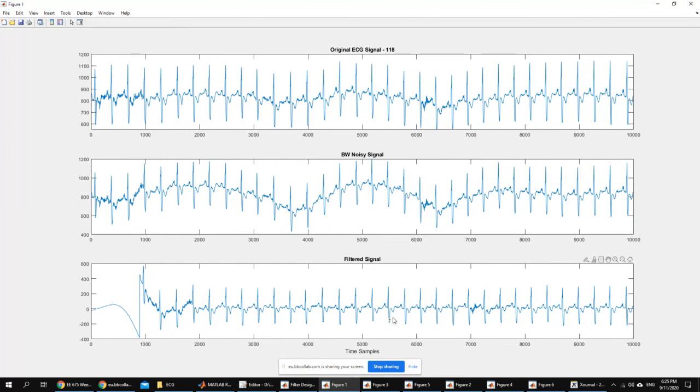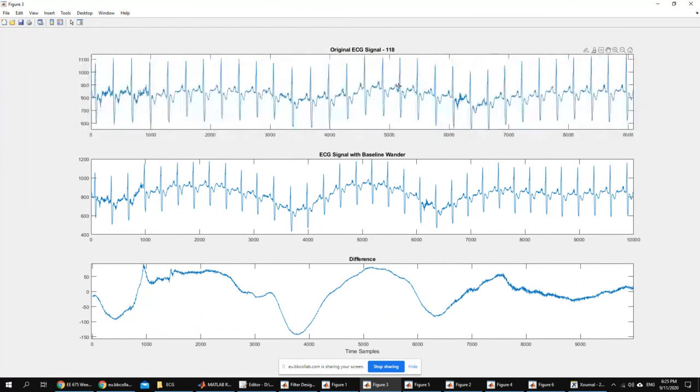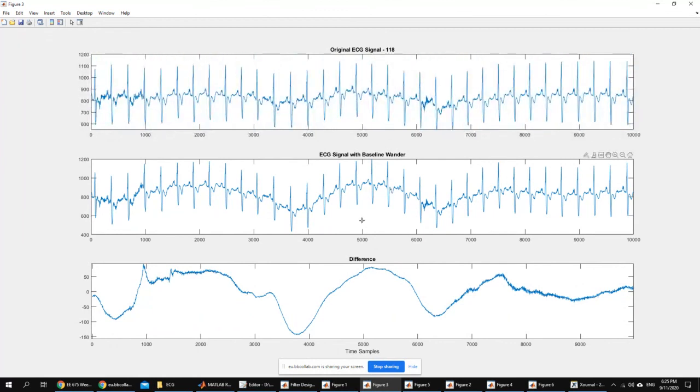acquiring during this course. Okay, what we did again was that we looked at this, sorry, just bring it back here. We looked at the artifact that we needed to remove. We noticed that it has a low pass character relative to the original signal, meaning that if I wanted to separate that from the original signal, I had to have a high pass filter.